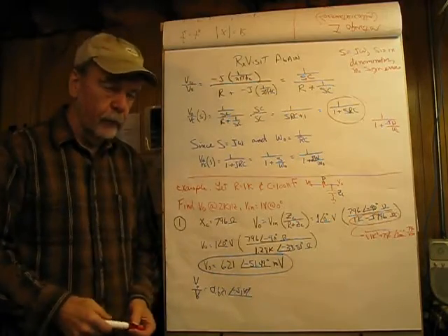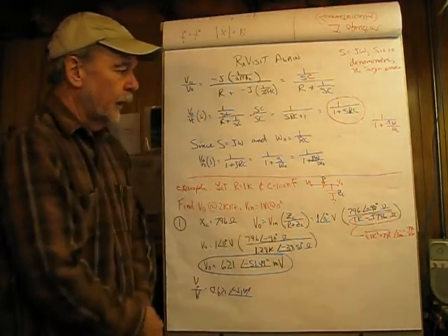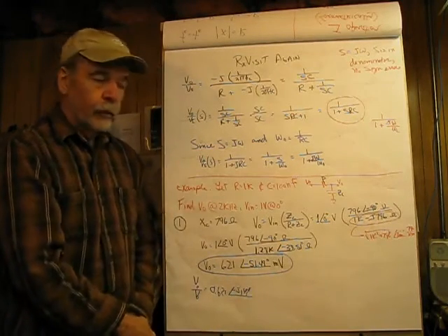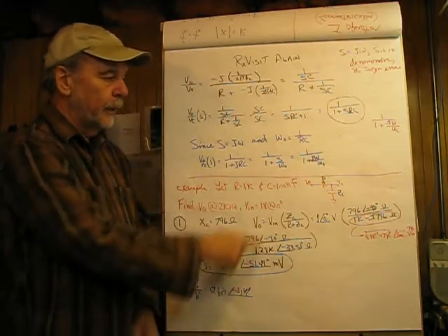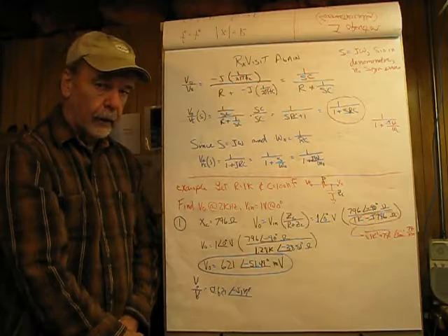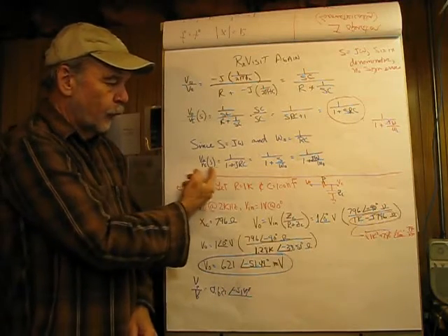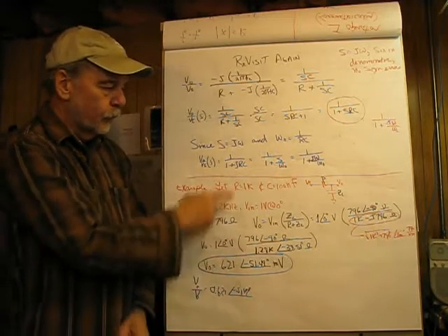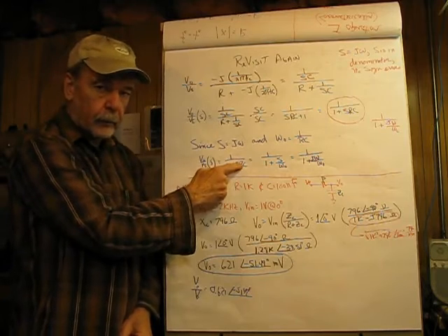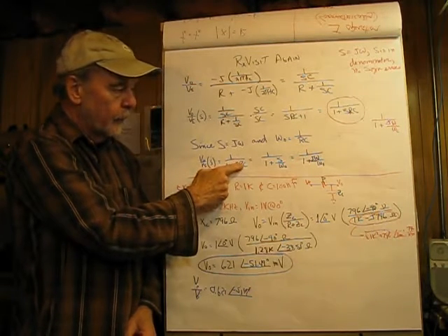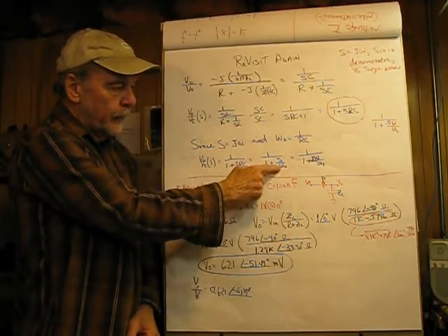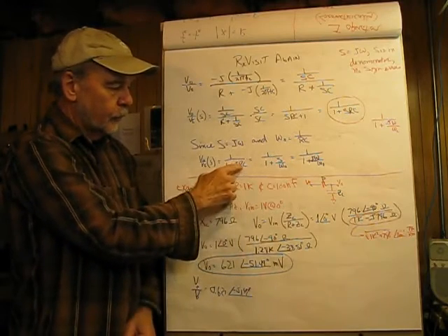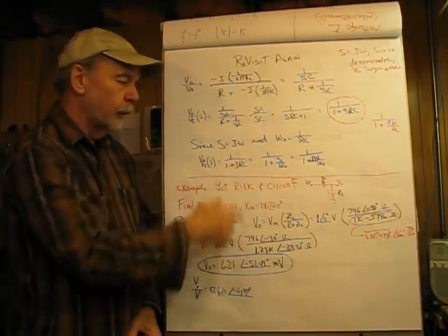So all is well. The camera stops at 30 minutes, so we're talking about this complex variable, and what we need to do is come down and remember that in our case here, S is equal to j omega, and omega 0 is equal to 1 divided by RC. We end up with a form which is 1 over 1 plus S over omega 0, and that's simply manipulating this a little bit, pulling the RC and substituting that with this right here in the denominator, since we have to take the reciprocal of both sides of this, since RC is in the numerator of the denominator.